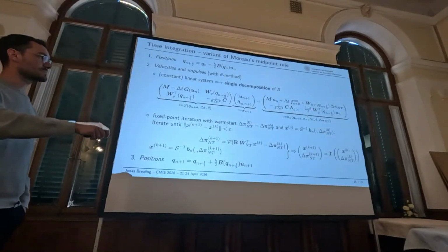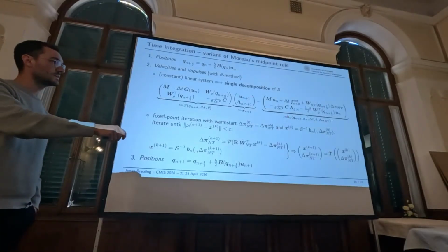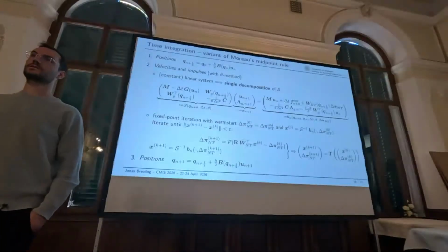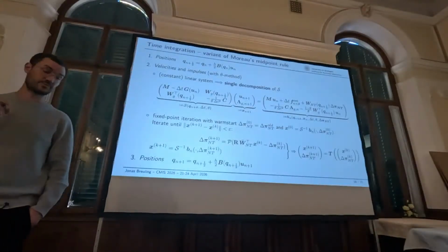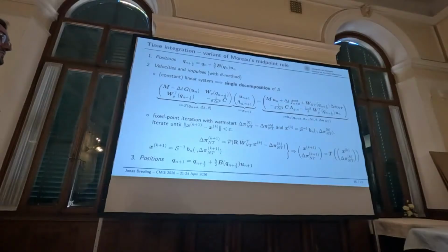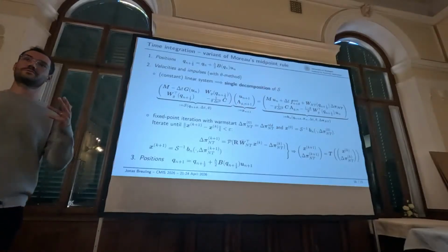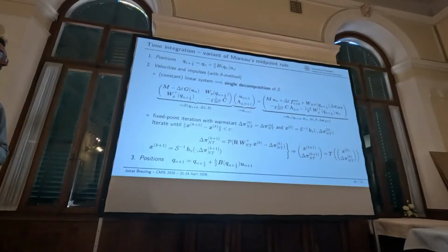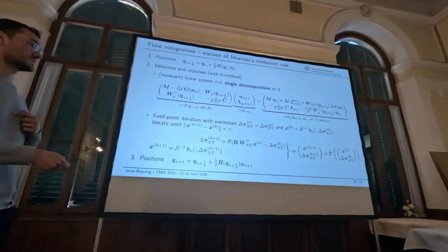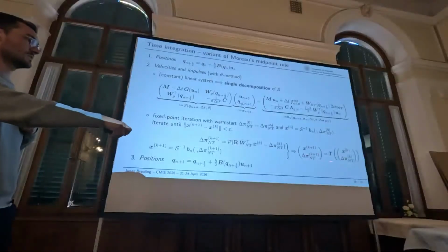The issue is that this linear system, I call the right-hand side B, depends on the unknown contact forces and friction forces. In order to deal with that, we somehow have to initialize these values and also the unknown velocities and these force laws. And then we can do an iteration. So we map these initial points to a new force, add the force again on the right-hand side, solve the linear system. And this can be iterated until convergence, which can be written as a fixed point iteration.